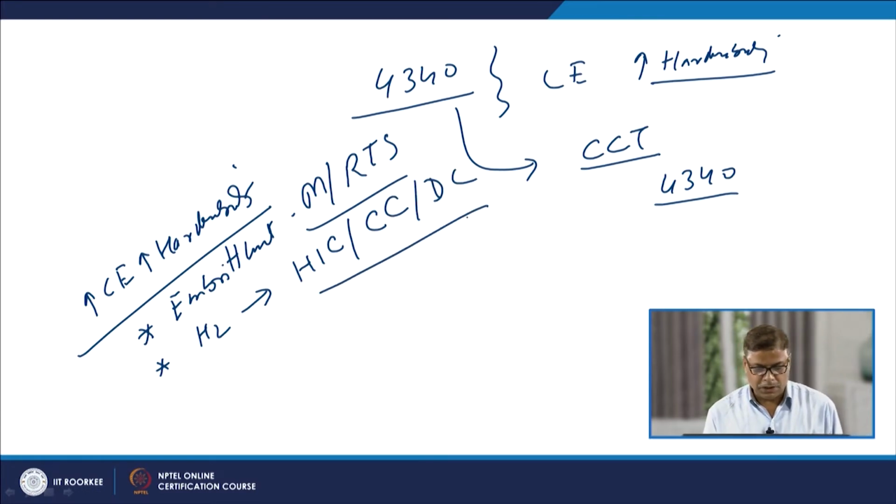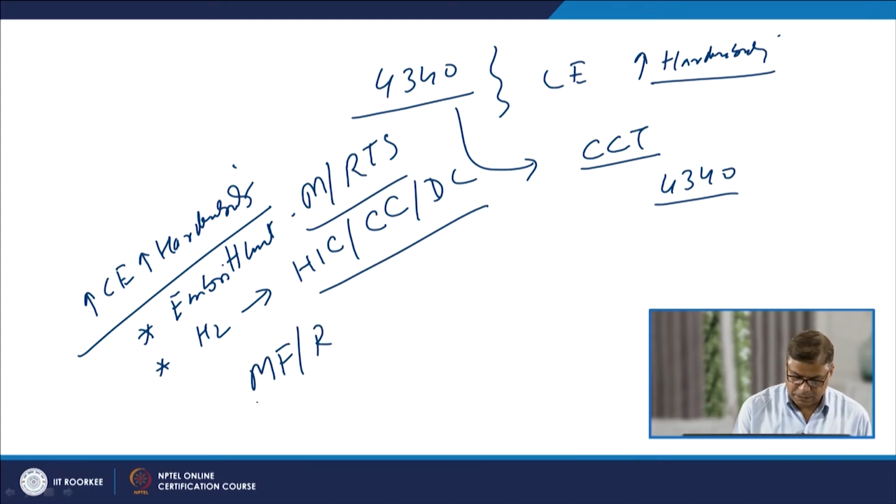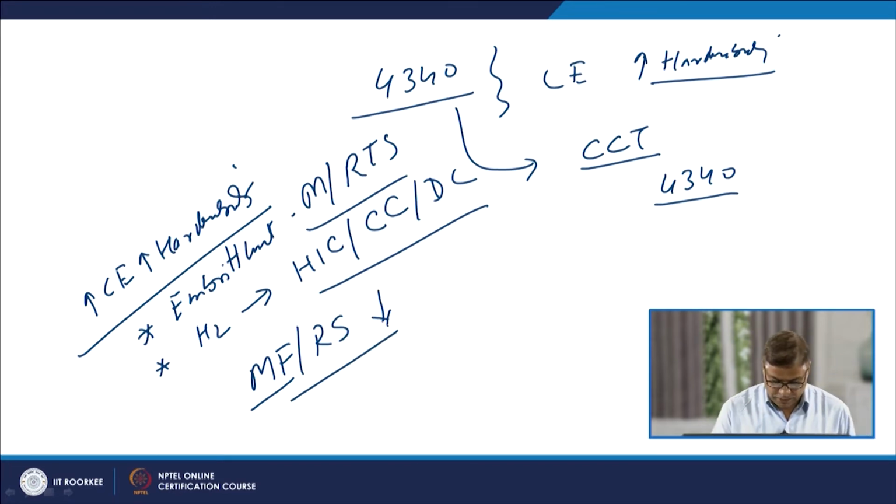In order to control such cracking, so that the heat treatable alloy steels can be welded without discontinuities and defects like cracks, it is required that martensite formation as well as residual stress development are both controlled, and the hardness is also kept at lower levels.